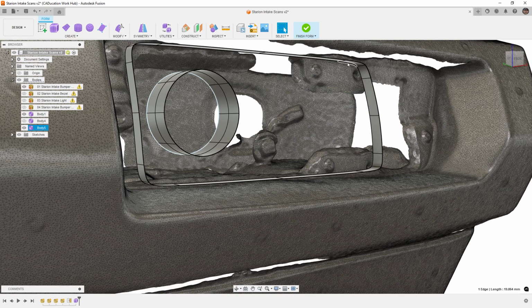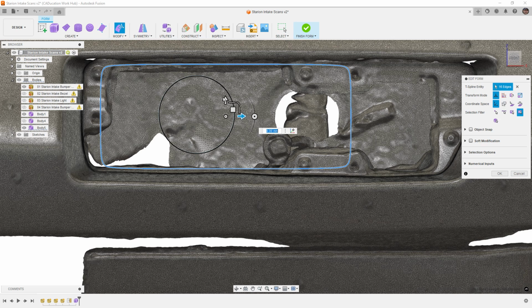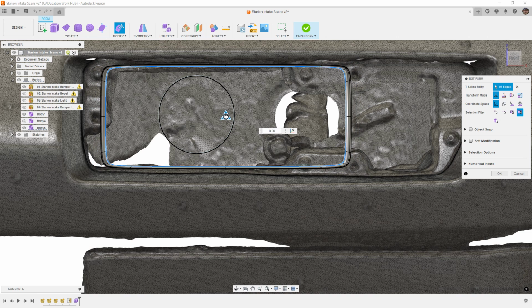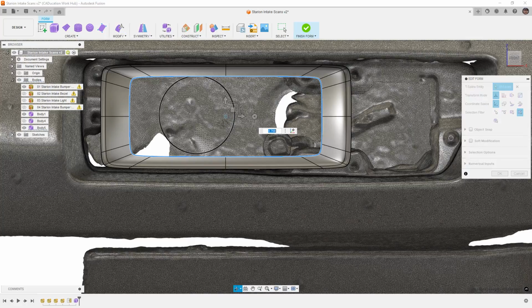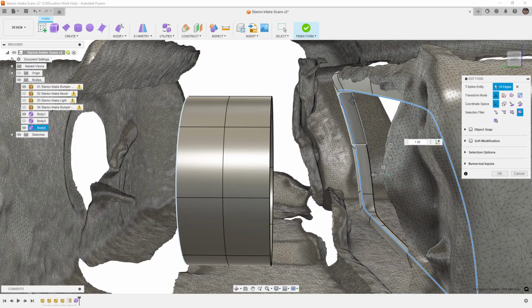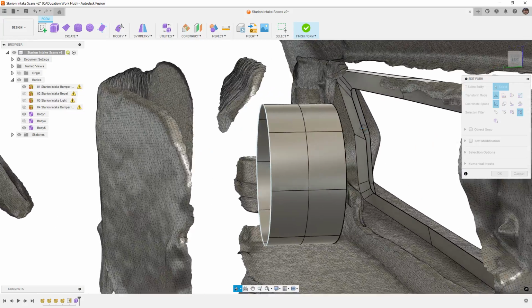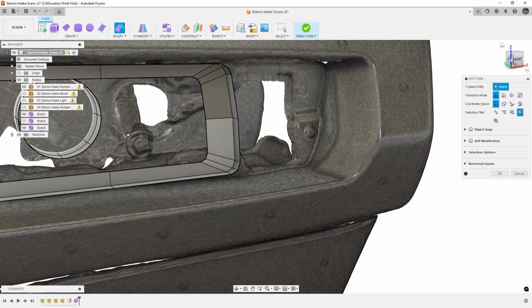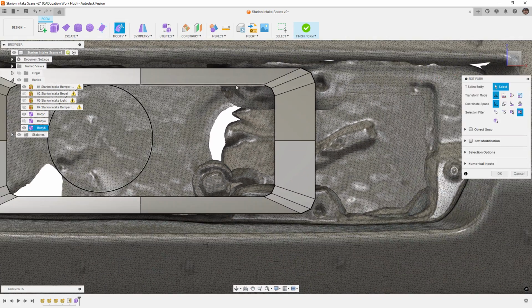So what I'm going to do is double click this edge, and from the front view with Edit Form, I'm going to hold down Alt, which is going to allow us to extrude a new edge. I'm going to scale it down to about there. And so what that did was basically took our shape and just scaled it inwards. I'm also going to go to box display. All right, so as I'm rotating this around, I'm looking for how far I need to go in order to avoid this.